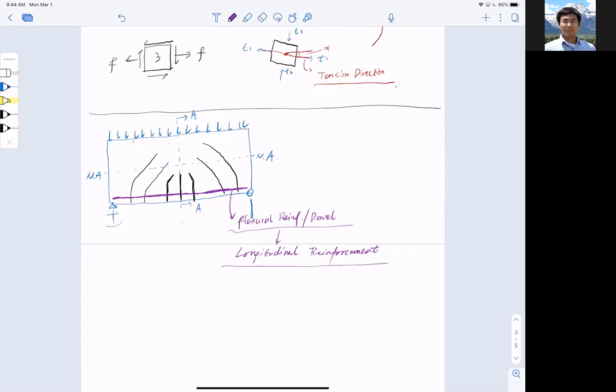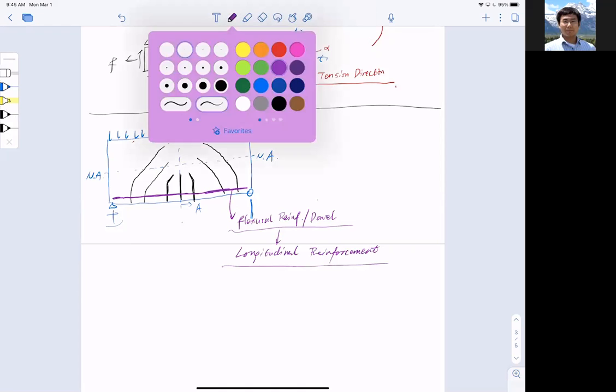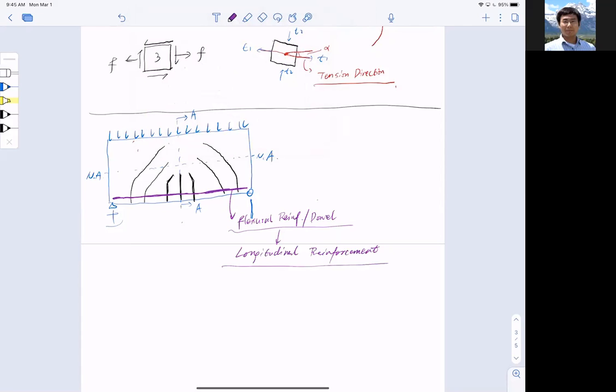All right. Now that is fine to take care of the cracks in the bottom, the concrete cracks in the bottom. How about the cracks in a diagonal direction? For these, I'm going to have a different reinforcing strategy. I'm going to put transverse bars. From the side view, it looks vertical, but transverse bars to resist these cracks. And I will provide a hanger bar to loop them through. So these are the stirrups, right? Or we also call them transverse reinforcement.